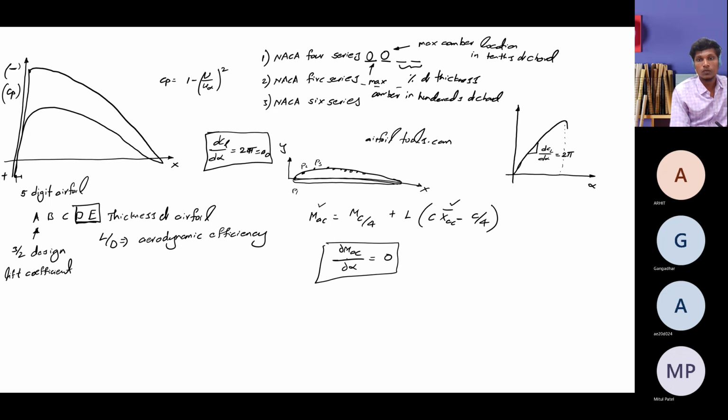So using these two equations, if you take one more reading at a different angle of attack, suppose this is MAC1 and MAC2, and if you see that MAC1 equals MAC2 and equate those two equations, then you will get the location of the aerodynamic center on the aerofoil. This is how experimentalists calculate the aerodynamic center if they want to design any aerofoil and find out its characteristics.